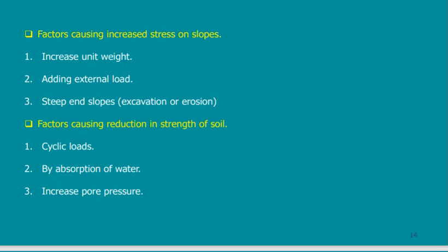If the soil itself is layered and each layer has specific parameters, of course each layer will have a different C and phi. If you have a very weak layer, then the C and phi will be very weak, and so on. This we will study when we come to the example of how to calculate the stability of the slope. We will draw a slope and calculate the driving forces and the resisting forces, and we will calculate the factor of safety.